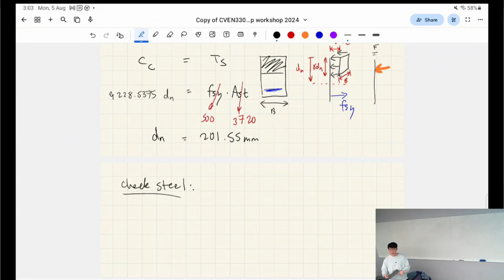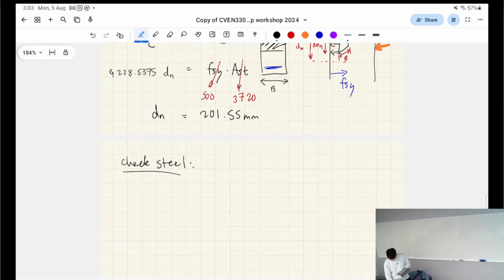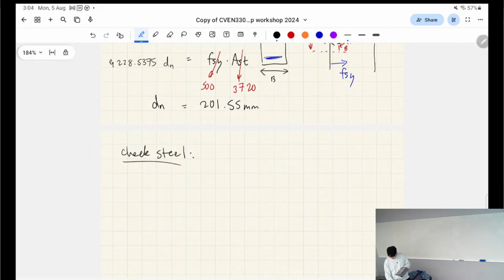What assumptions are we assuming? So for singly reinforced concrete, we just assume the steel was yielded, right. If we check it and it's not, it means our assumption was wrong, you have to redo it, right? So if you've assumed that your tensile bars haven't yielded, but they actually have, you gotta redo it. That's why I'm telling you, if you have tensile steel, it's usually yielded, okay? Okay, so how do we do that? It probably helps to draw out the strain diagram.